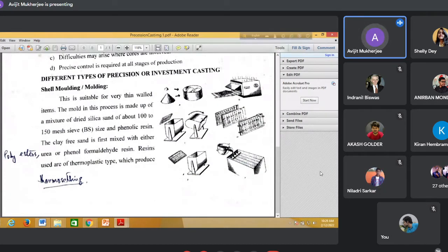And set the temperature for some time. What is the time? What is the temperature? Again, after some time we shall mention. But previously heat the pattern, the metallic pattern, not the wooden pattern. Mind that, not wooden pattern. Here a metallic pattern is needed because on the metallic surface you can provide the shape and geometry very easily, so that the pattern will not be damaged after some time. And a wooden pattern can't be heated in an oven.